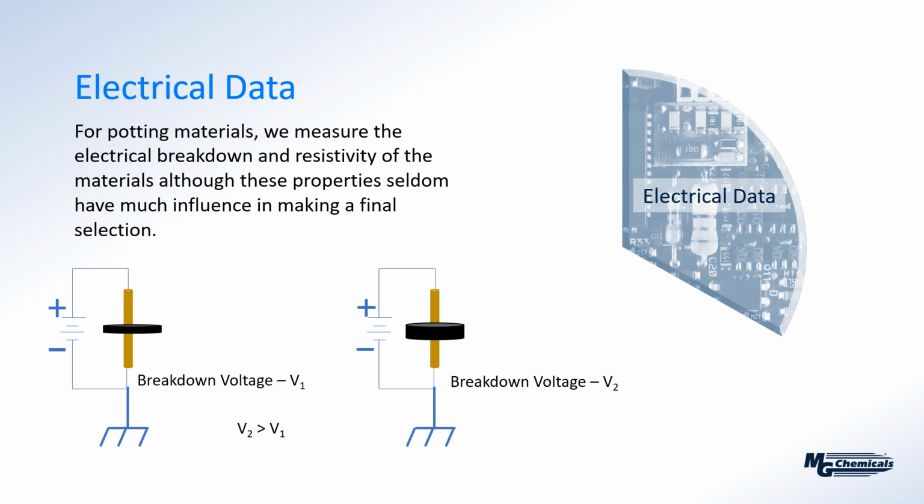The only thing preventing a short is the fact that your sample is insulative. It's preventing the two contacts from shorting each other out. So you simply ramp up the voltage until the static charge is enough on the surface to cause a breakdown through the sample, and then again it shorts, it grounds, and the test stops.